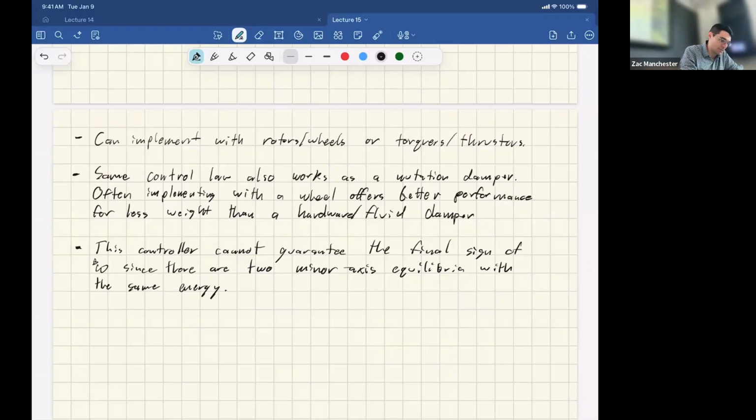Okay, so you need at least three of these. So you know how to figure that out, by the way. Being fully actuated is equivalent to this B matrix having full rank. So this thing has to have rank 3 for me to be able to produce any output torque. If I look at each one of these little blocks, what's the rank of one of them? I'll leave this for you to think about.